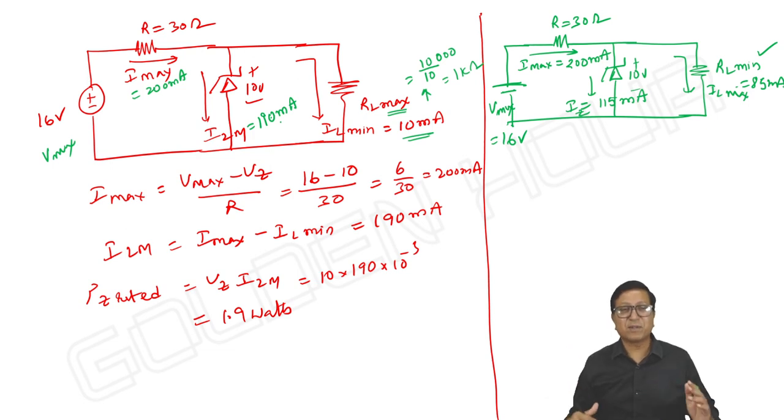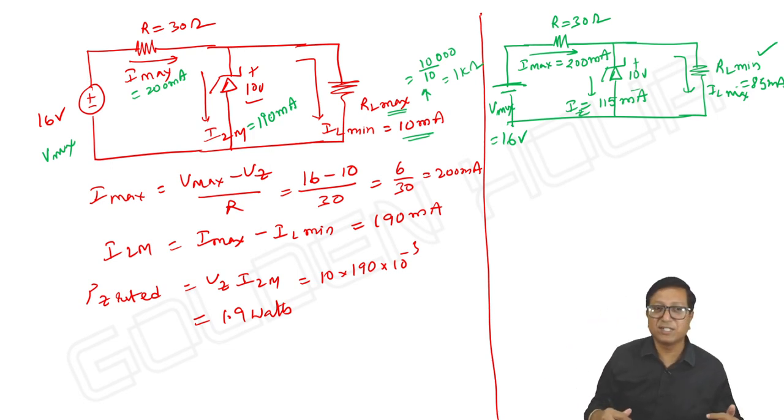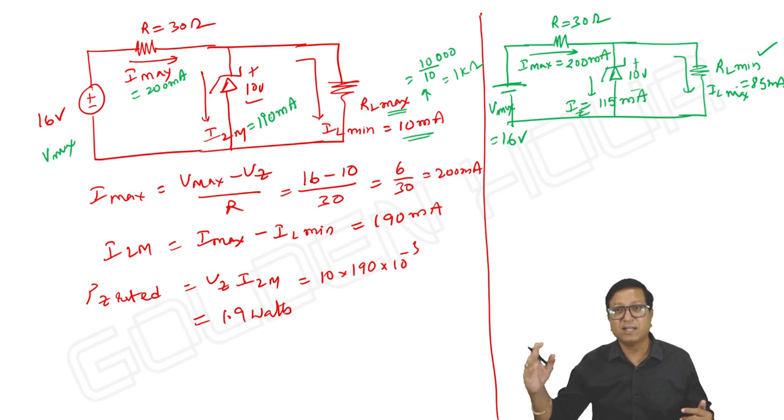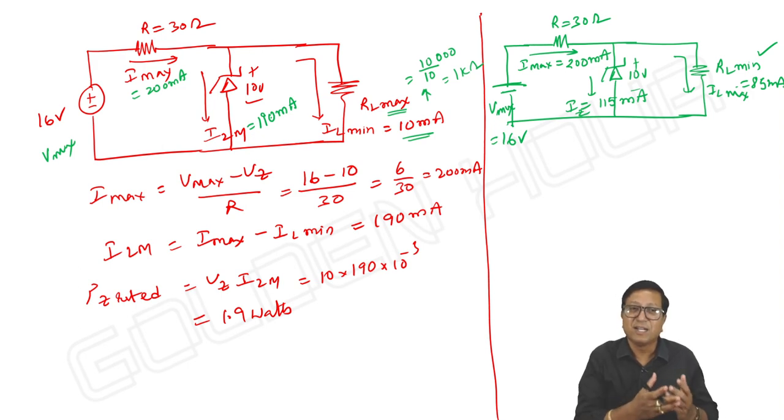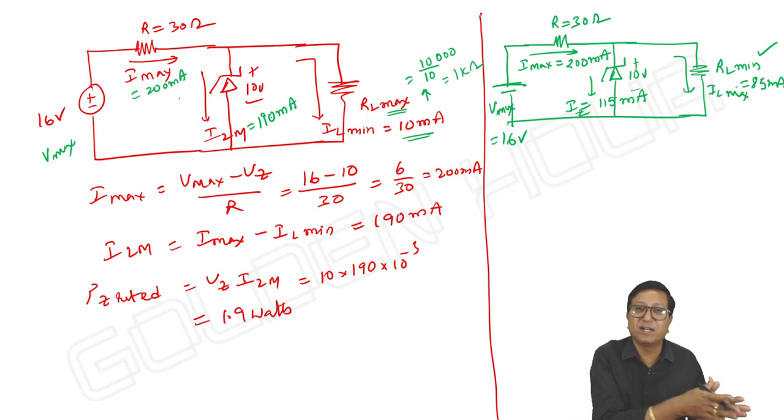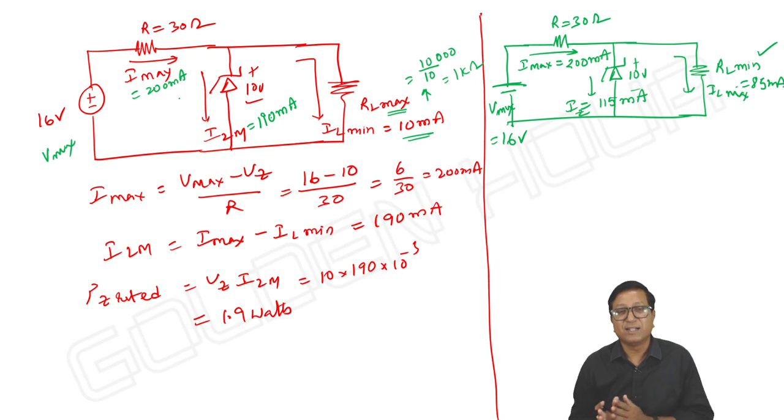So whenever you vary the input between 13 volts to 16 volts and RL between 117.6 ohms and 1 kilo ohm, the Zener diode will adjust. It is not mandatory for I to increase continuously. I is independent of RL. I depends only on input voltage, and IL varies depending upon the value of RL, and IL never depends upon your input.